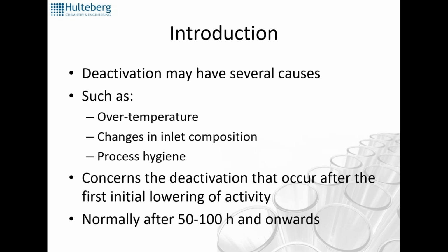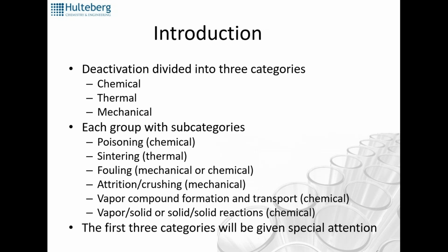And then after 50 to 100 hours, that shakedown period is sort of over, and this discussion is around what happens after that. And we divide deactivation into 3 different categories: chemical, thermal, and mechanical. And then you can go on and break down each of these categories into finer bits.